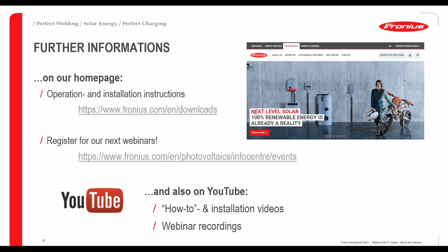One question was regarding the dynamic peak manager. Is it possible to retrofit that on a system? No, unfortunately not. So you have to use one of the latest inverters of FRONIUS. This is the Snap inverter range. So for example, the Primo or Symo inverters, as well as the new generation, the Gen 24 inverters. So that's basically only on those. Also the Galvo has the dynamic peak manager integrated.